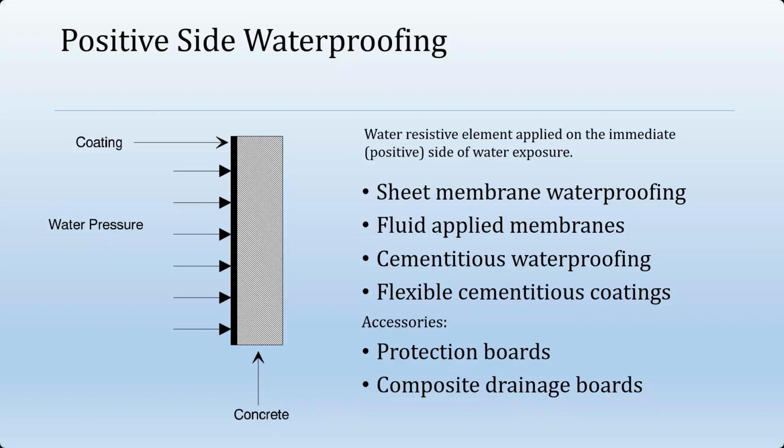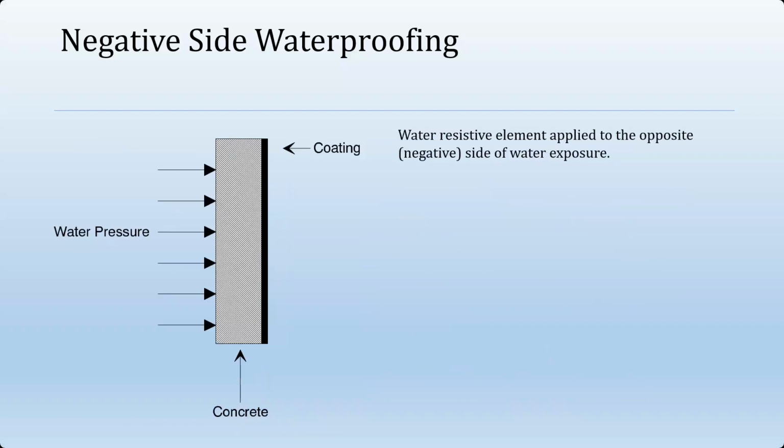It's not uncommon, obviously, to protect waterproofing with rigid insulation, which is pretty much qualified by all manufacturers as a means of protection. But if we want to really do the system correctly, then we'll also add a geotextile drainage mat, aka drain board, on top of that. Now I'll get into that here in just a moment.